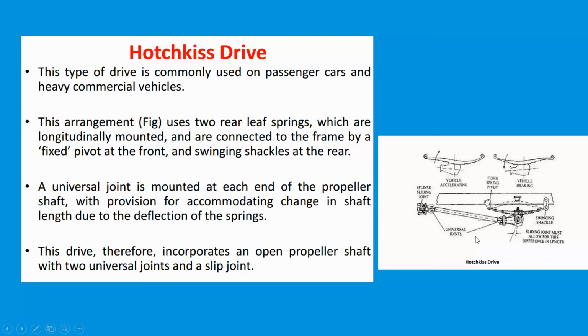Shaft drive consists of a drive shaft called the propeller shaft extended from the transmission in front to the differential in the rear. The differentiating characteristic of Hotchkiss drive is the fact that the axle housing is firmly attached to the leaf springs to transfer the axle torque through the car body.